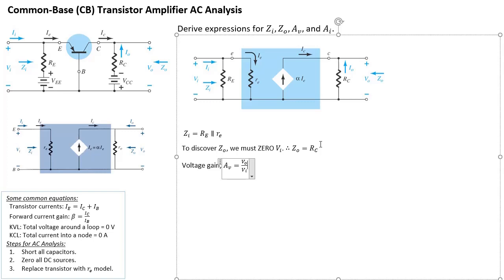Okay. So the expression for VO means the voltage across, in this case, RC. Well, IO is defined as going up. So to figure out what VO is, obviously you need to reverse IO, because VO is pointing up and IO is also pointing up. So if you want a positive VO, then we need a negative IO.